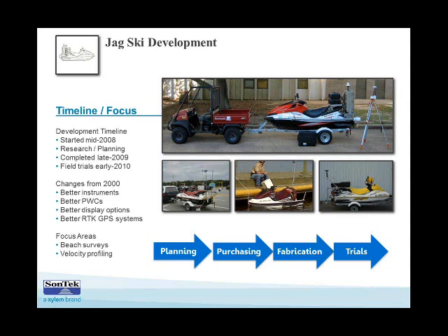Moving on to the next bullet, make sure you provide a good, stable RTK setup that's got line of sight, preferably line of sight to where you're going to be working. And then be prepared to have multiple setups if you're working across a large area like we are. So we can go out and pound some stakes into the ground early on and flag them and record the elevations.